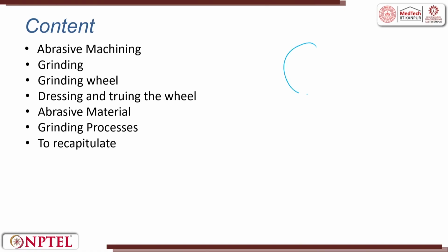When we have a cutter and we take a cross section of the cutter, you will see teeth. In that tooth, if you do a further cross section, you will see clearance angle, relief angle, flank, everything there. So, that is why I did not go deeper into it, but friends, you should keep this in mind. Here also you have positive rake, negative rake, everything.